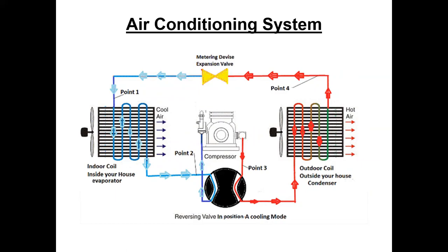It's like 38 degrees. That working fluid's 37, 38, 39 degrees. Well, if you're 38 degrees, a 75-degree room looks pretty darn hot, right? And so you put that cold refrigerant through that coil, and all those little kilojoules or BTUs or whatever you want to think, they go hopping from the air through the coil into the refrigerant. Okay? So then all that heat goes into the refrigerant.